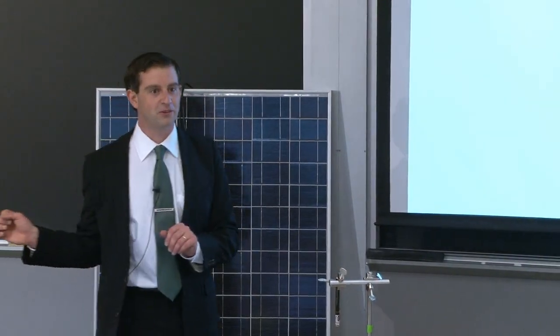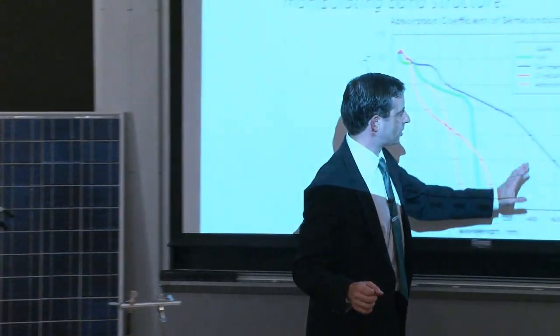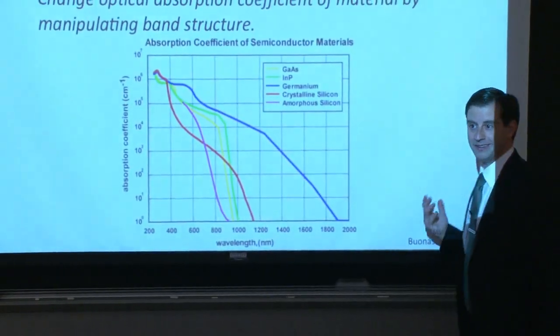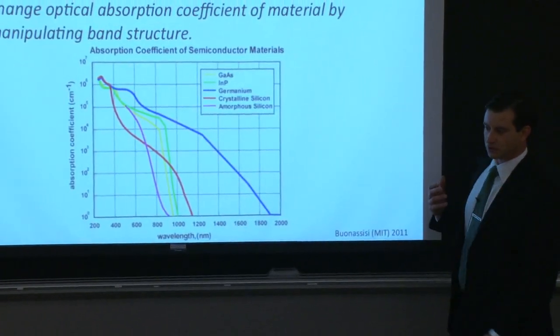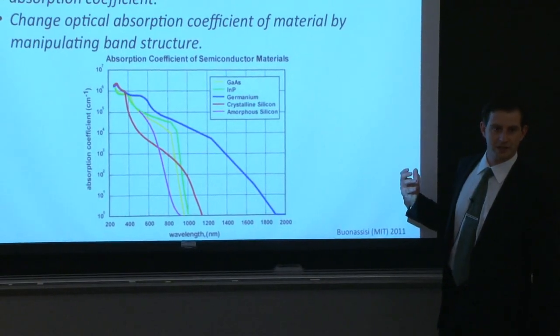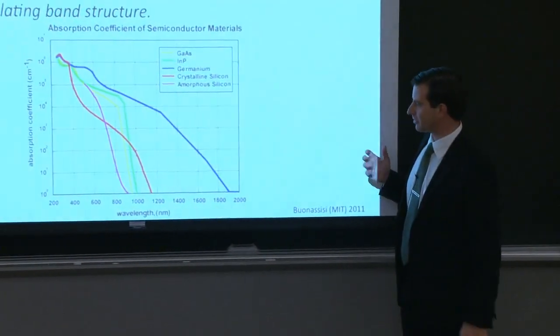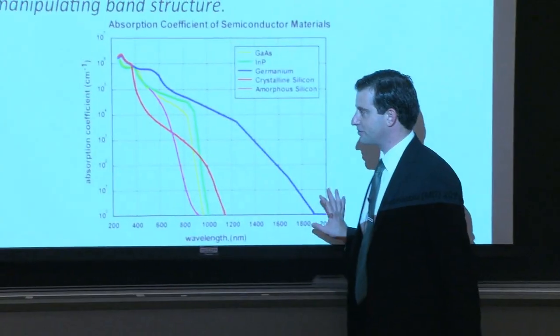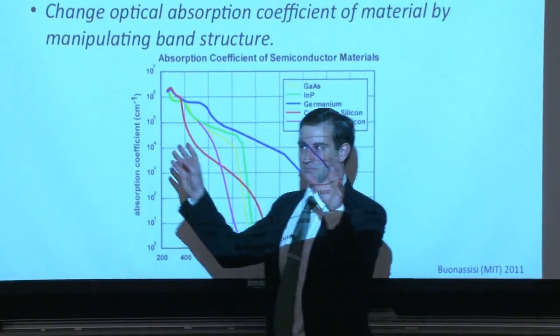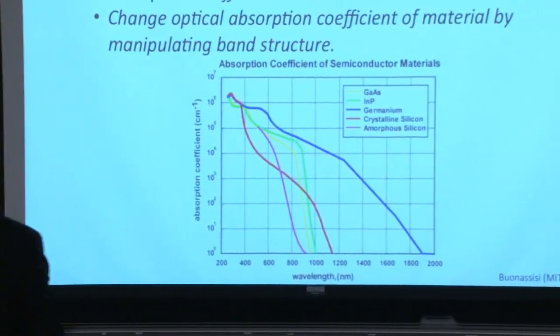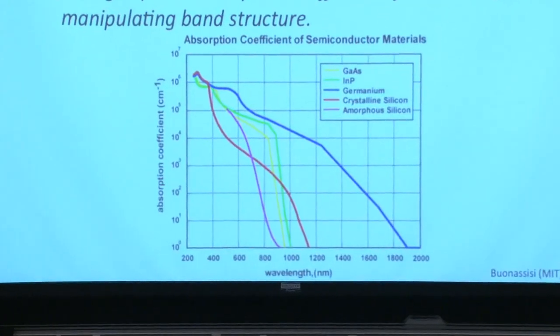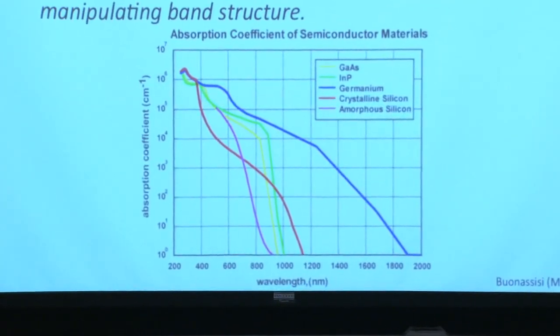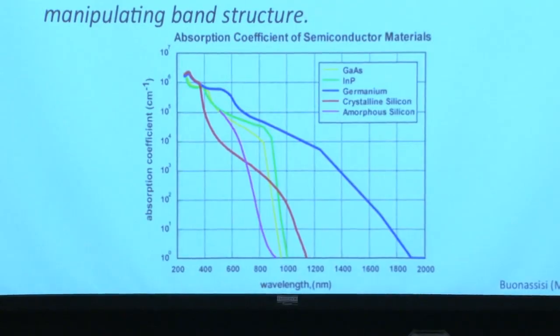It has additional benefits as well. If we can eliminate the longer wavelength stuff out here, which is heat, performance of most solar cells suffers when they get hot. And we'll learn why that is about 5 or 10 lectures from now. And so if we manage to do spectral upconverting or reflect that long wavelength light away from our device, we can improve performance there as well. That's another form of light management that doesn't necessarily involve light trapping.